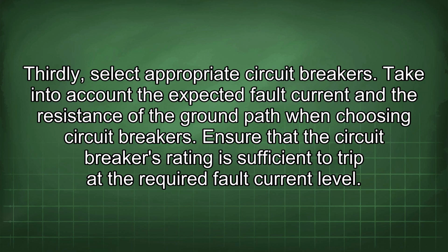Thirdly, select appropriate circuit breakers. Take into account the expected fault current and the resistance of the ground path when choosing circuit breakers. Ensure that the circuit breaker's rating is sufficient to trip at the required fault current level.